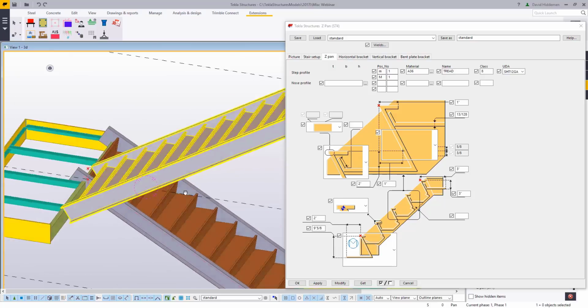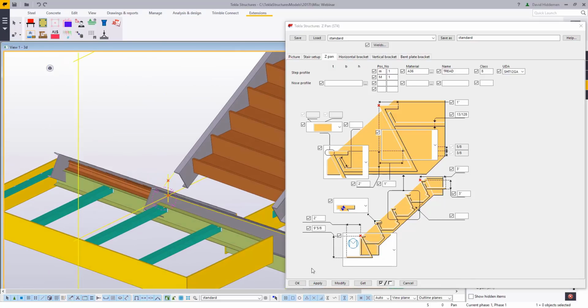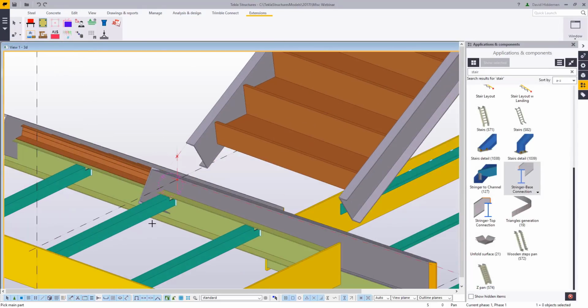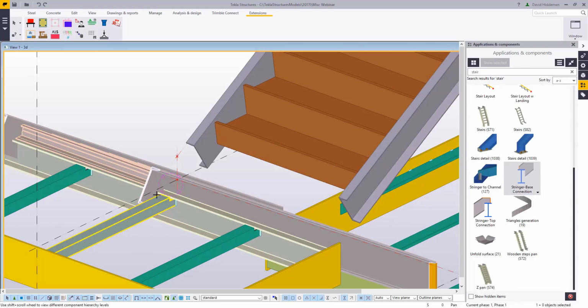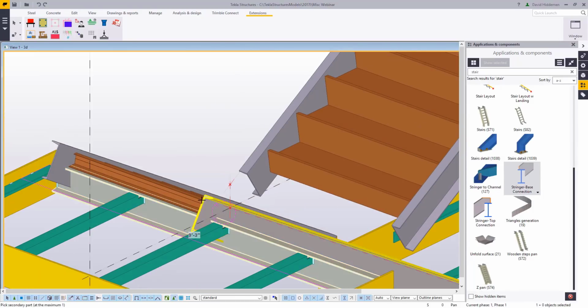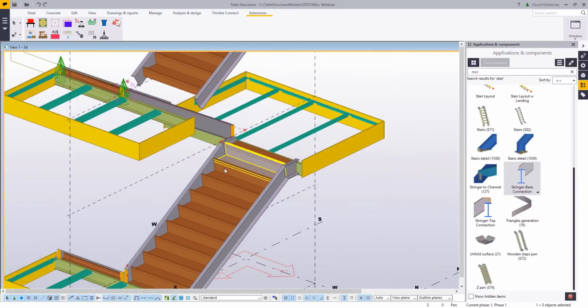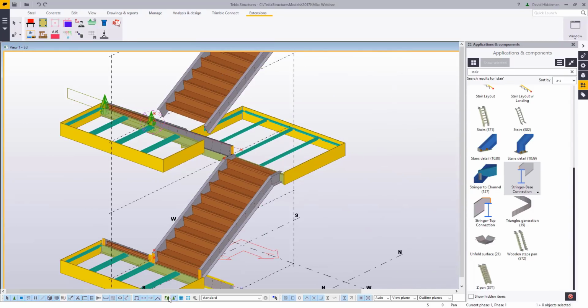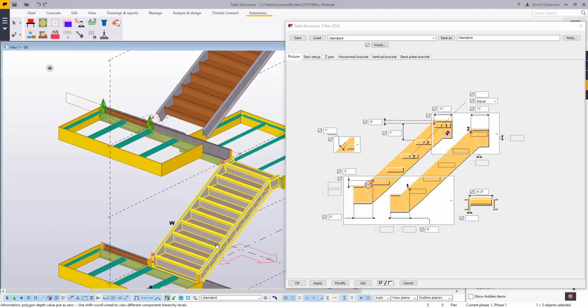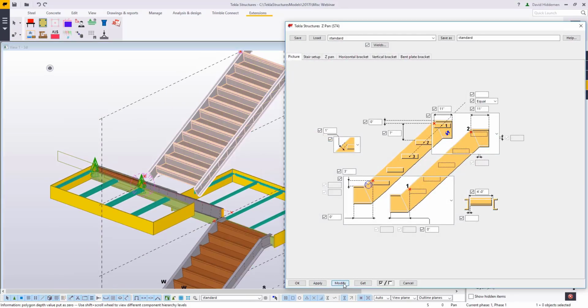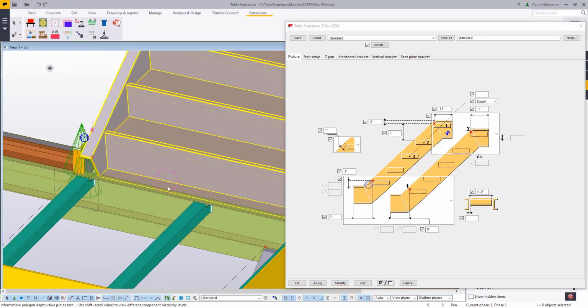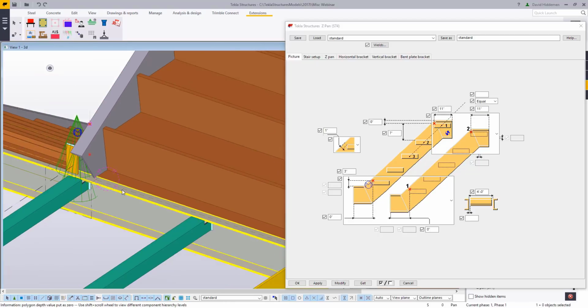But the basic stairs, as you saw, were very, very fast to put in. Let me finish off just a couple more here. I want to try to complete this as much as I can. Okay. And you know what? This stair and this stair are very similar. So what I'll do is I'll kind of borrow the properties of that. We'll extend the bottom down. Looks like the dimension even worked out for the pan itself.